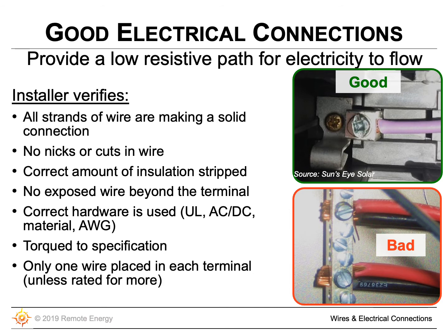And in that lower picture, you can see one strand is sticking out of that bus bar with a set screw. And when I was an apprentice, the electrician I was working with saw that I had done that, and he said, you know what, if you can't get all the strands of that wire into that hole, you might want to pick a different profession. So ever since then, I've thought, yes, I'm rushing, I'm trying to get this job done, but let's make sure that we get all those strands inside of that set screw.